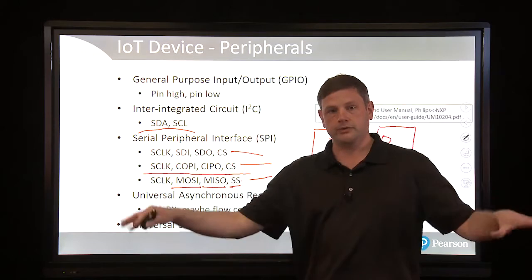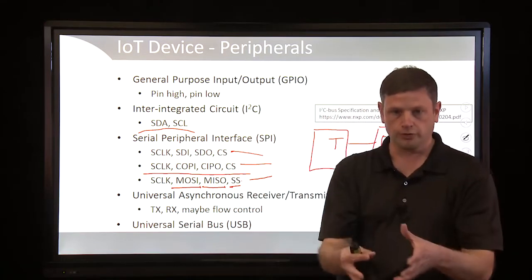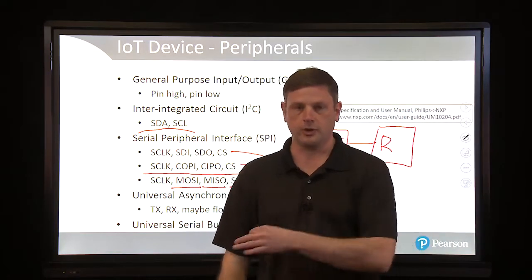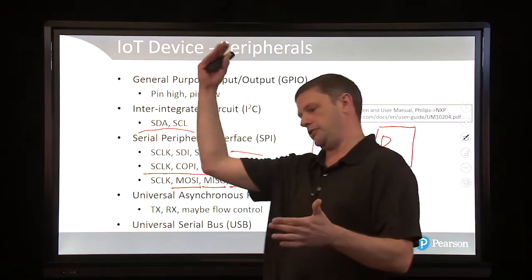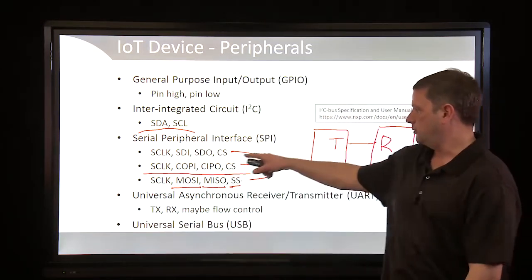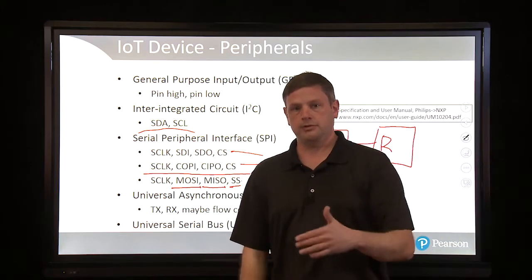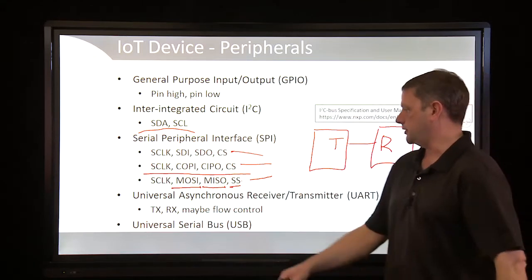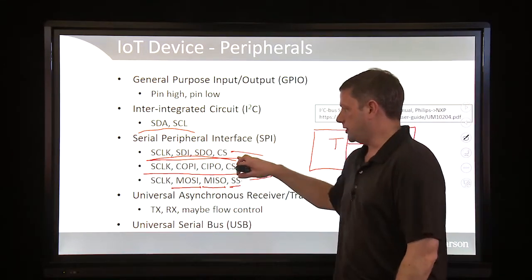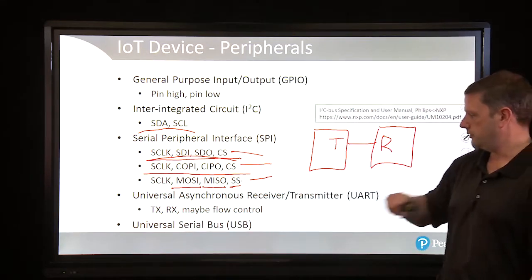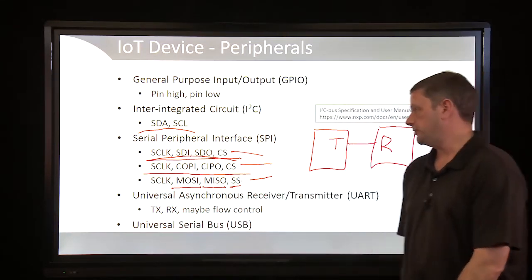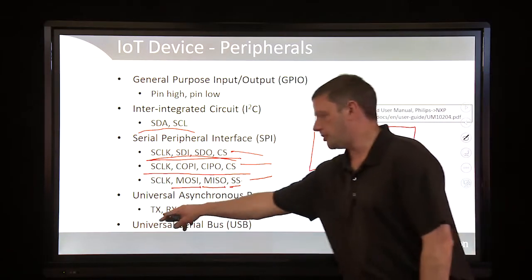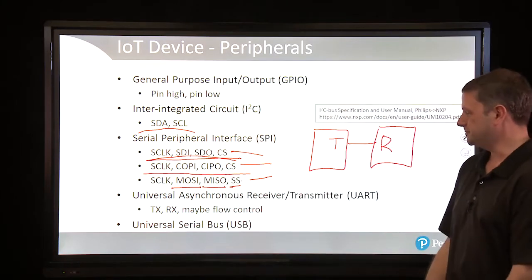SPI is a bus. You have the controller device, controller out, and peripheral in. It's always the same direction. There is no ambiguity there. It's leaving the controller and it's being received by a peripheral. With SDI, serial data input, now we're talking about, is it input to the controller or the peripheral? Who knows? Sorry about the little tangent, but this particular terminology leads to ambiguity that is very similar to the ambiguity that we have in UARTs. This problem's been around for 50 years: the perspective when talking about the transmit signal.